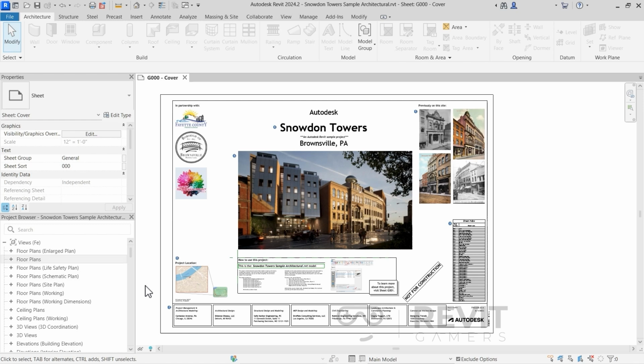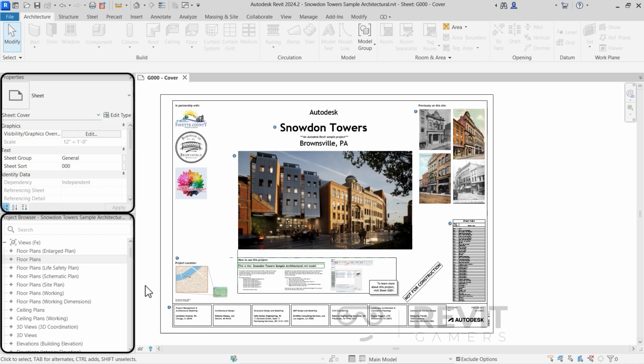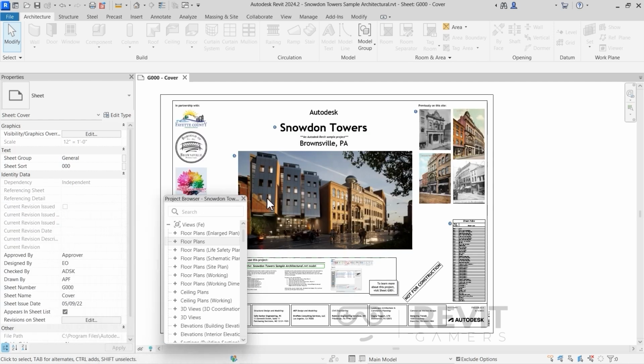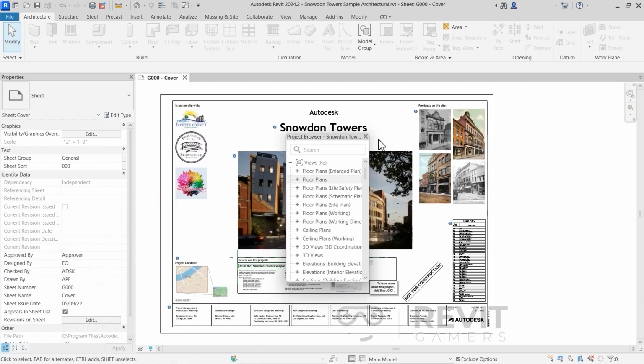our project. After installing Revit, this is the configuration of the Revit interface. On the left, there is the Properties palette, and down the Properties palette, the project browser is located, but their location can be easily adjusted. So, if I hover over the top of the project browser or the Properties palette, I can drag them out and put them in the floating mode.